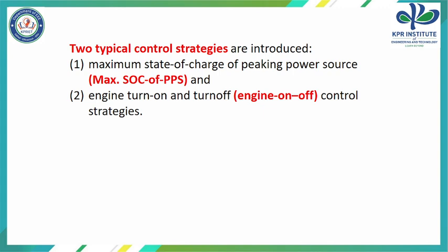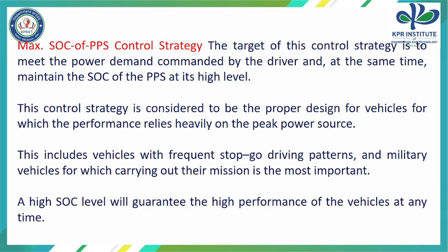Let us discuss maximum state of charge. The maximum state of charge of peaking power source control strategy is a strategy to meet the power demand commanded by the driver, and at the same time maintain the SOC of the peaking power source at a high level. So we have to give the power for all the components, and at the same time ensure the battery charge stays at a high level.